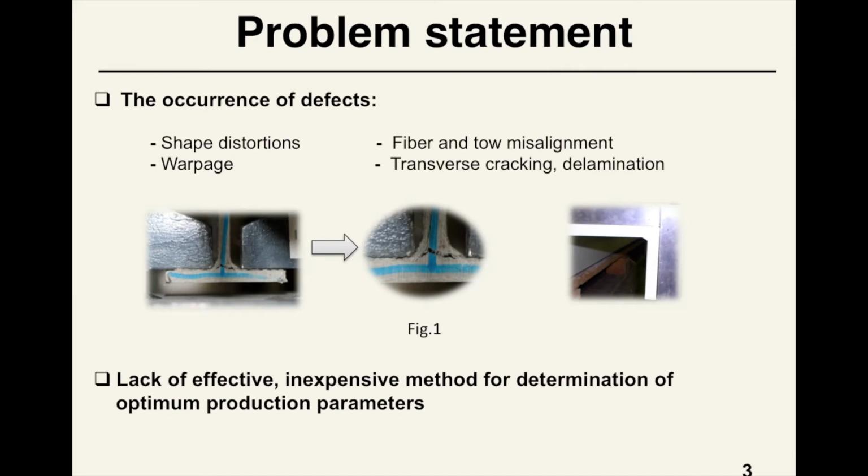In recent decades, increased attention has been paid to a deep understanding of the processes caused by residual stress in laminated composites, specifically shape distortion and possible damage of the product at the stage of manufacturing. The presence of residual stresses in the composite material affects the occurrence of such defects as delamination, warping, as well as the appearance of microcracks in the matrix of the material, which has a significant impact on the static and fatigue strength of the final product made of composite material.